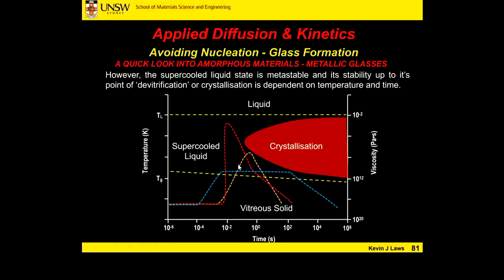We can do some forming process. And then we go, okay, we're very close now. We have to cool it, because if we go over this line, we're going to start forming crystals. So we have to cool it back down below Tg again. Below Tg, the atoms don't move very quickly, so it cannot nucleate to form crystal. Oh, I see. Okay, thank you so much.